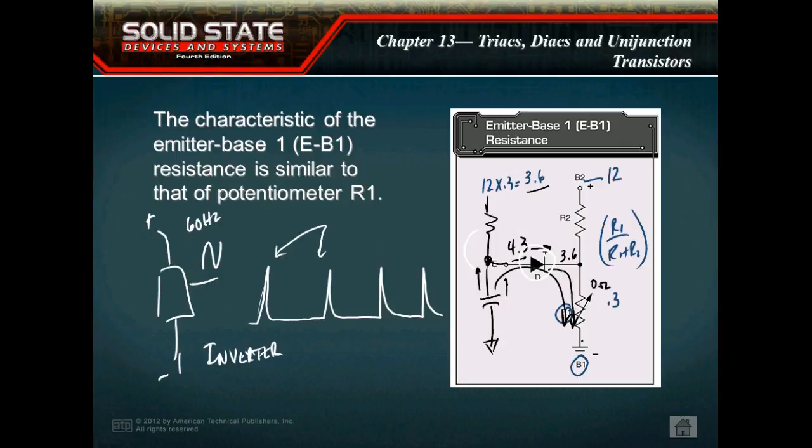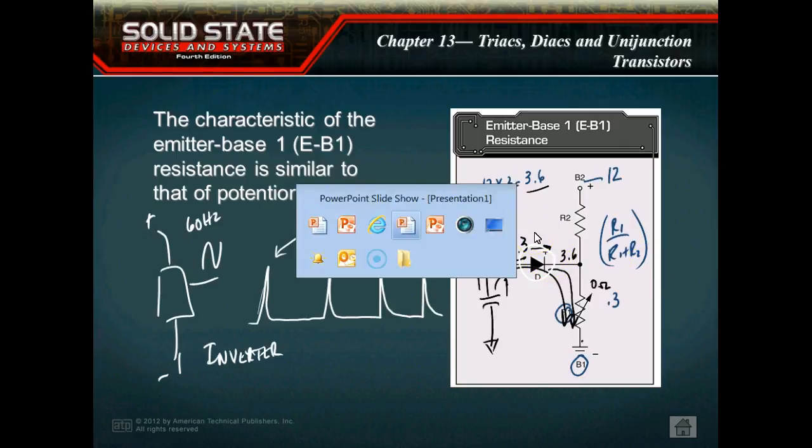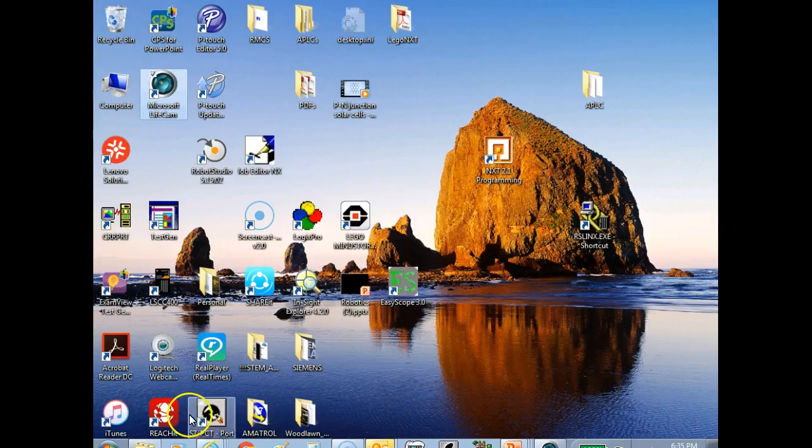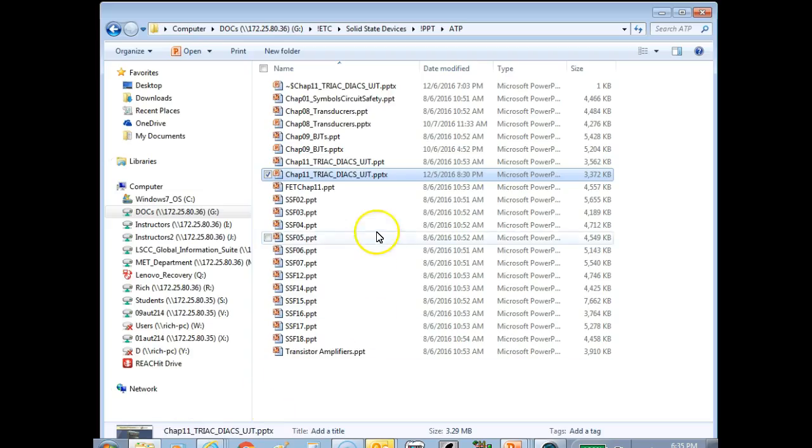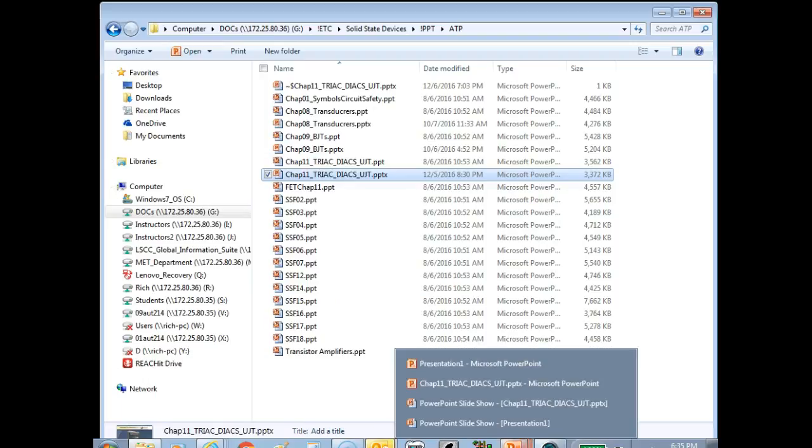And what we would do to set the frequency of oscillation is the size of this resistor right here, a resistor and a capacitor. And it probably has the formula somewhere. So if we look at our data sheets, that's what we'd be looking at.